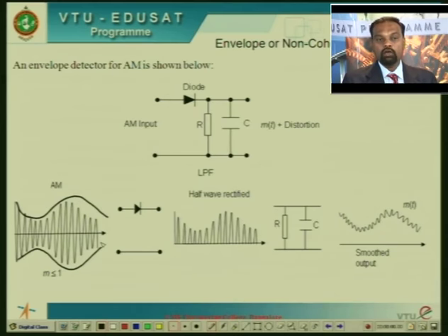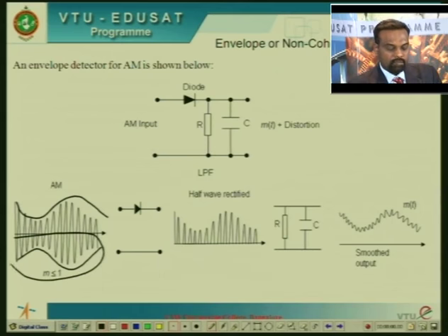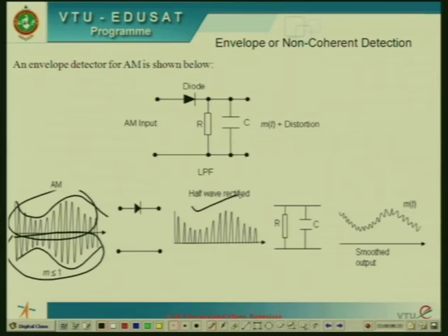So what will the diode now do? Because the diode is working as a rectifier, whenever the signal is applied, it will cut off all the signals on the bottom side, because they are all less than the cut-in voltage of the diode. All the positive data available here is available at the output of the diode.